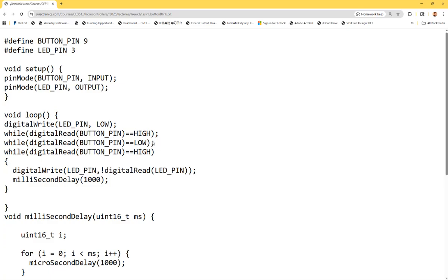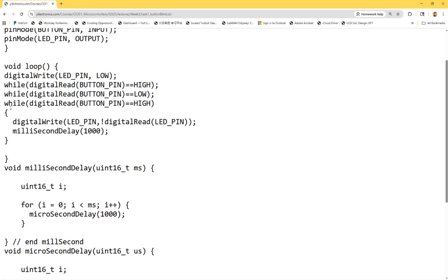You push it, it stays here. So when your finger is still holding that button down, it stays here because that's the low. It detects the low and it's a dead loop. It's going to stay here, and then you release it. What's happening? It becomes high again, and this while loop, keep in mind, there's no semicolon because you do need to do something, right? So when you release it, it becomes high again. So you need a curly bracket to have all the behavior, all the actions in here. That's how that works. So it's detecting that push and release action, and after push and release, it will stay in high afterwards, and it's going to stay in this while loop. It's a dead loop.